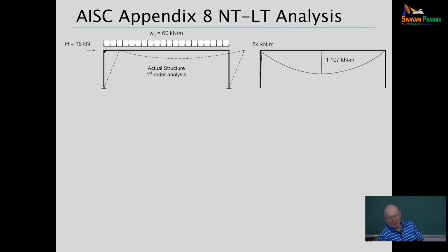So for starters, let's say we did a structural analysis on the frame I just showed you. In that case, this frame would have lateral deflections like you see shown in the dash lines and moments. Clearly the dominant moment is actually in the roof girder, but those small moments in the left-hand lateral load resisting column are of course very important.